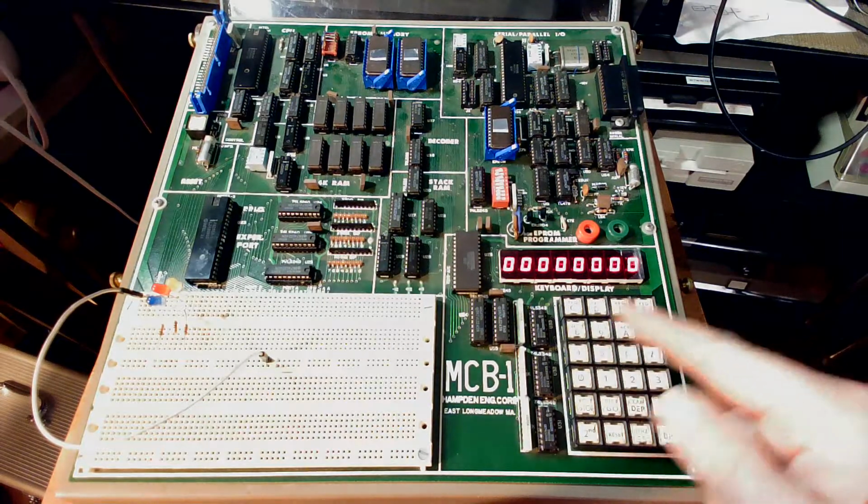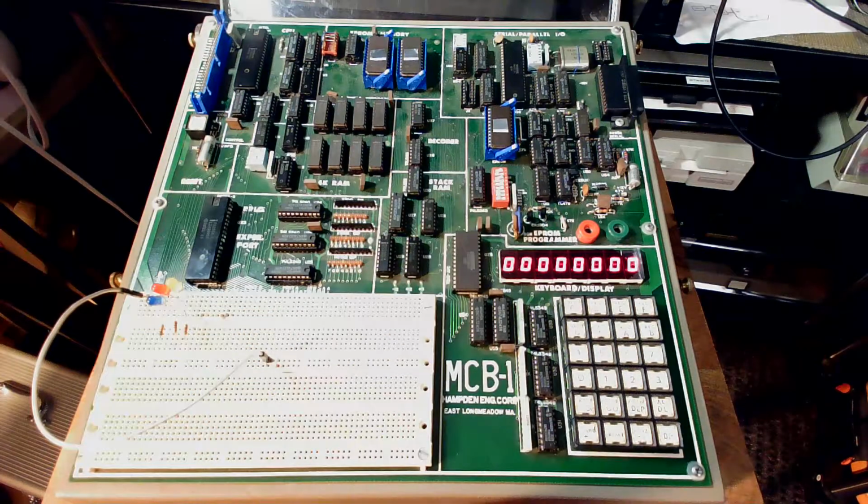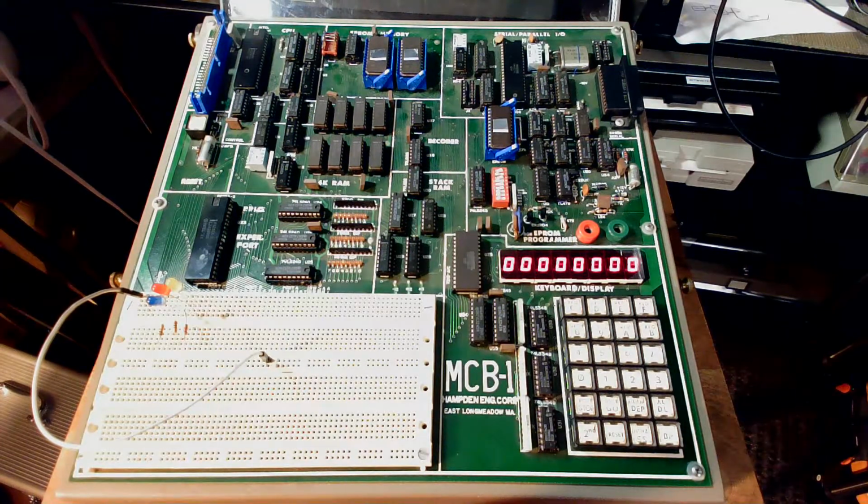So basically whenever a key gets pressed, it generates a restart 6.5, and this generates an interrupt basically for the 8085, and then a restart is being executed, and that restart then basically reads in from the IO bus the key that had been pressed. It debounces it, it decodes it, and so on. So that's a complicated story, and actually also the 8085 interrupt masks play a role here.